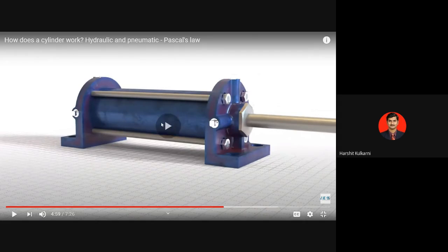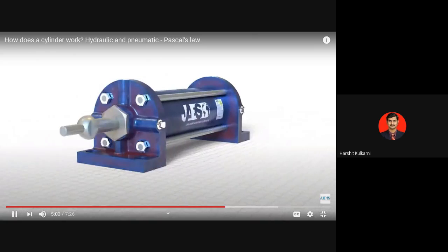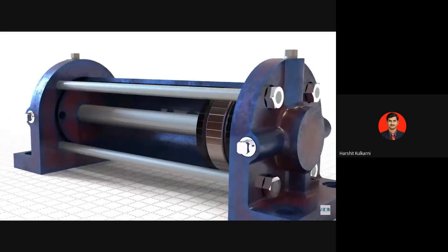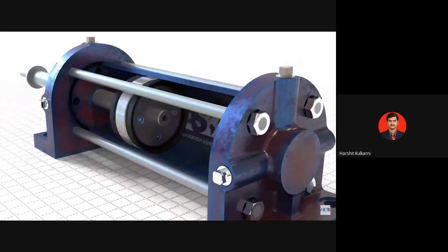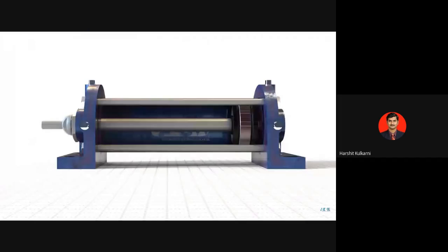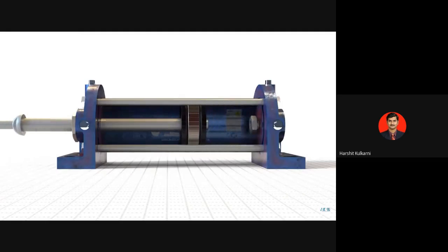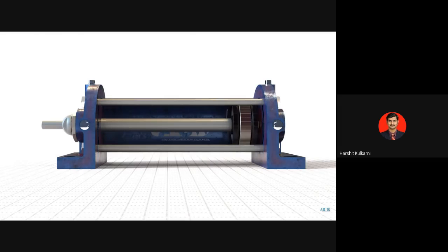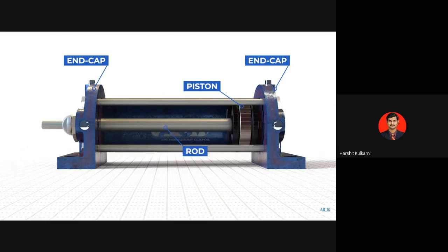They provide accurate linear and or rotary movement, and they can be used in harsh environments, even in extreme temperatures. Light and requiring little maintenance, they generally produce less force and a lower speed than hydraulic or electrical systems, but they remain an economically advantageous alternative. The key components of a pneumatic cylinder include end caps, a piston, a rod, a scraping seal, a guide, and sealing gaskets.